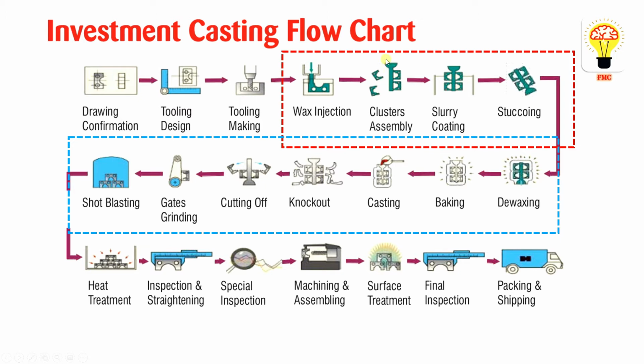You can see this portion is the top here, and here it was tilted over, and finally it is put in a downside shape so that the wax will come down. You will get the perfect shapes. When the shape is available and there is no wax, then we pour the molten metal over that shape. Remember, this is made of ceramic, so it can withstand high temperature, nothing to worry.